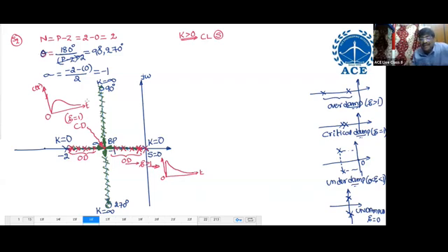So if K is still increased, what happens? The poles are complex conjugate. This total range is for what? Underdamped system. What is zeta? Greater than 0, less than 1.